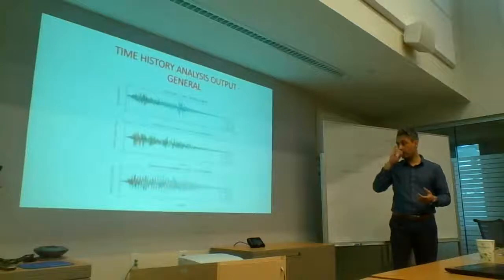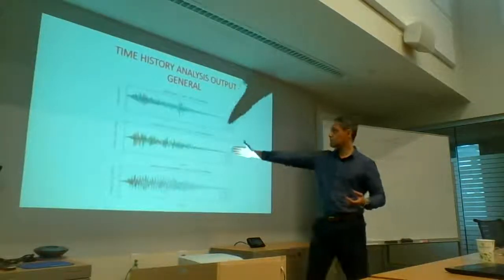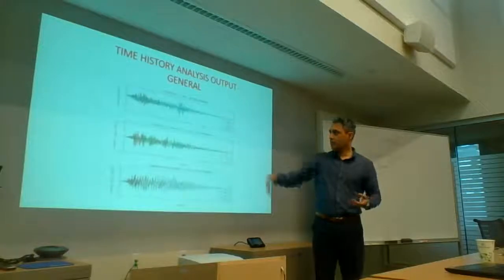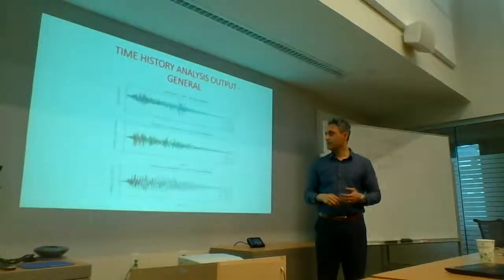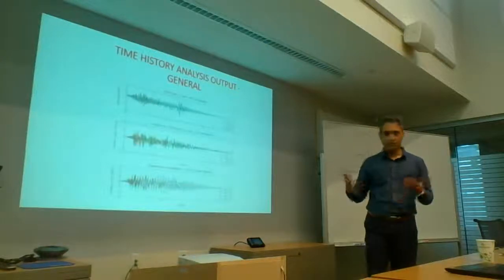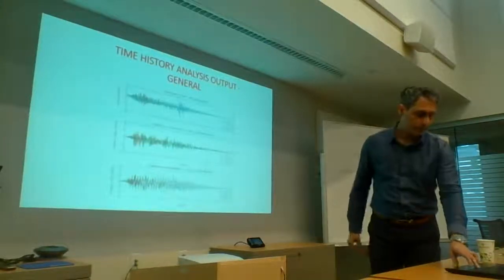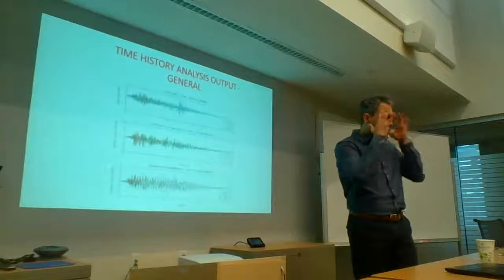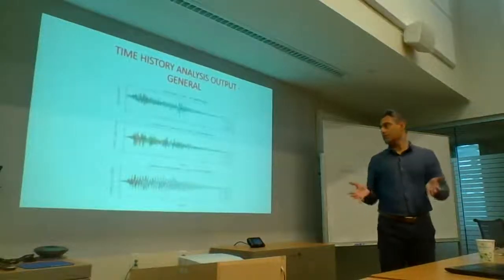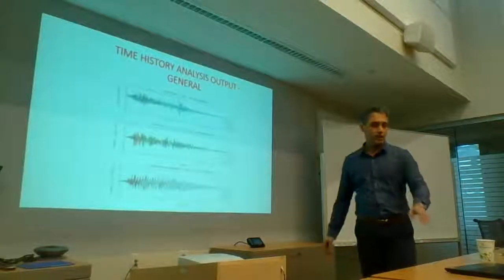It's going up and down. My bending moment, this is sort of the strong motion part of it, I'm going from 5 meganewton-meters to -5 meganewton-meters, and longitudinally I'm between 3 to 4. So if you are just looking at tables, you'll tend to get lost. It becomes imperative that we start to plot things.